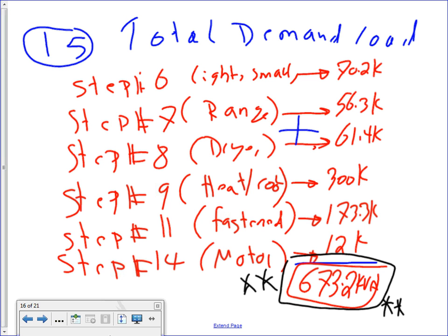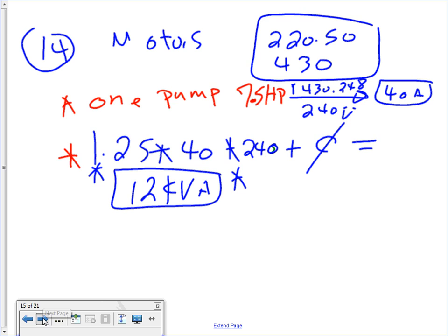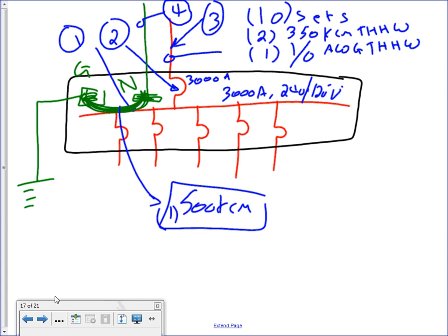Okay. Now the goal is to size, again, back to the sizing. I keep collecting these here. The goal, guys, is to size, number 1 is the panel. Number 2 is overcurrent protection device. Number 3 is the conductor, the grounding electrode conductor, and the main bonding jumper.